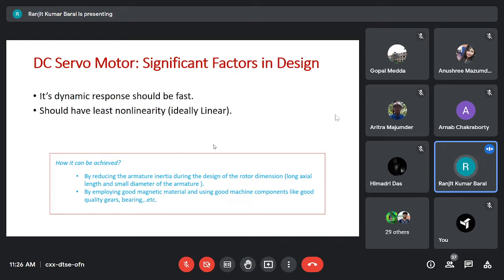Now, the other point, that is increasing the accuracy, that means decreasing the steady state error. How to reduce the steady state error? The easiest way is to reduce the non-linearities that might be affecting the system. Non-linearities that are present within the system and affecting its steady state performance. The other thing on which the steady state error depends is the type of the system. You cannot do anything with the type of this system. Okay, you cannot do anything.